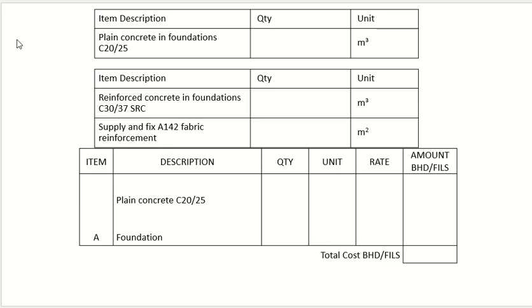Okay, but these supporting items, they have a specific name. The point was that the rate will be including these things, supply and fixing and everything. So this is the quantity part. Now if you want the cost for the first scenario, you will take the quantity, the units will be cubic meters, the rate will be per cubic meter, and the cost will be this into this.